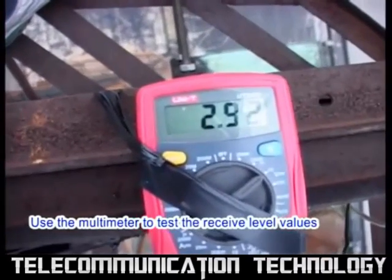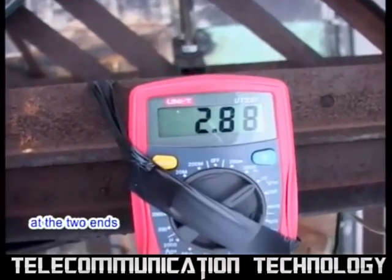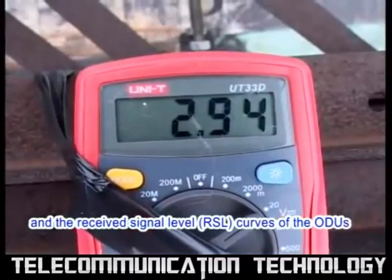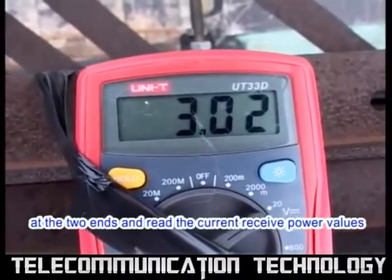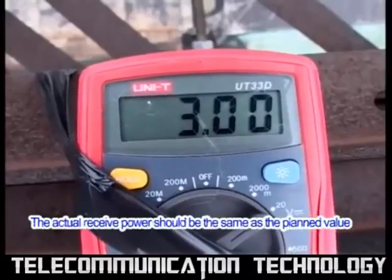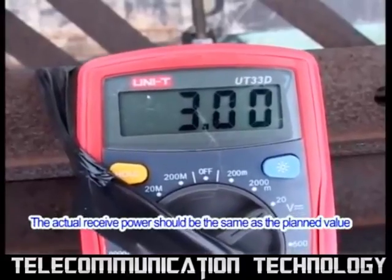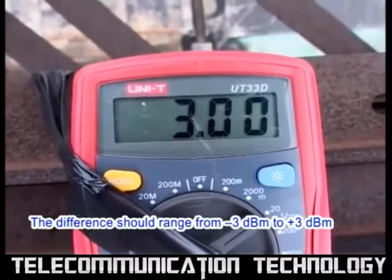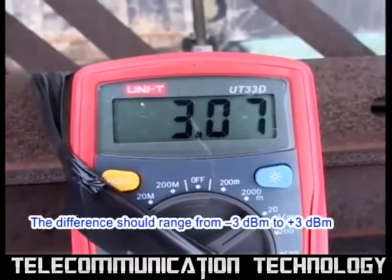Use the multimeter to test the receive level values at the two ends. Refer to the receive level values and the received signal level curves of the ODUs at the two ends and read the current receive power values. The actual receive power should be the same as the planned value. The difference should range from -3 dBm to +3 dBm.